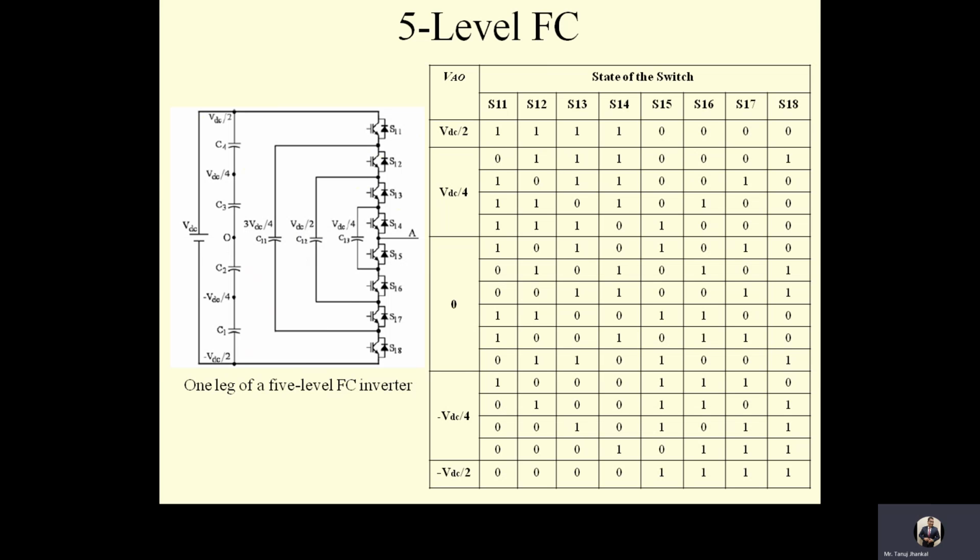In inverters where the number of levels is high, the control also becomes complicated as the voltage across a large number of capacitors has to be maintained by ensuring proper duty ratio in the switches. But the same amount of energy or voltage storage in the capacitors provides better ride-through capability to this class of inverter against input supply interruptions.